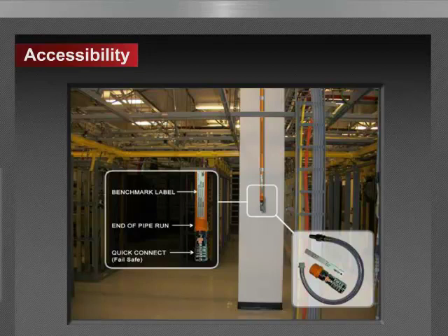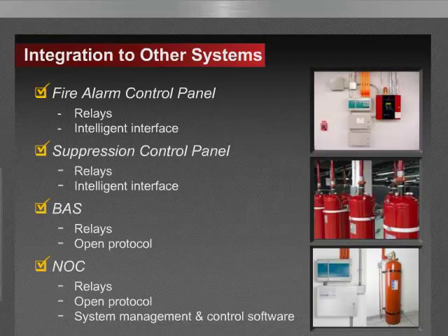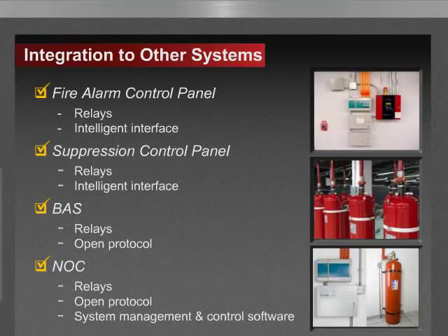Here's a specific question. Sounds like the person asking this question specifies this type of system frequently. They ask, how many computer room air handlers can realistically be covered by a single pipe on a multi-pipe detection design? It says manufacturers seem to recommend one pipe per air handler, but they've heard of instances of up to 4 units being covered by a single pipe. Does that make sense? Yeah, it does, and it depends largely on the velocity of air going through the air handling, the size of the air handling unit, the size of the grill.